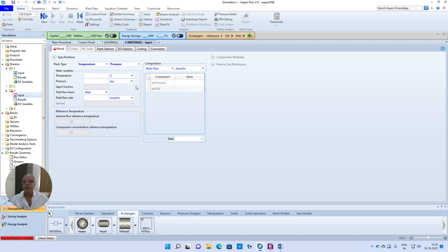Next. Because I did not specify any other component, let me take water, steam. The maximum temperature, you can say, probably vapor fraction 1, saturated vapor, maybe at 2 bar. This is a wild guess. The flow rate, because that was 1000 moles per hour, let me also take 1000 moles per hour of steam.